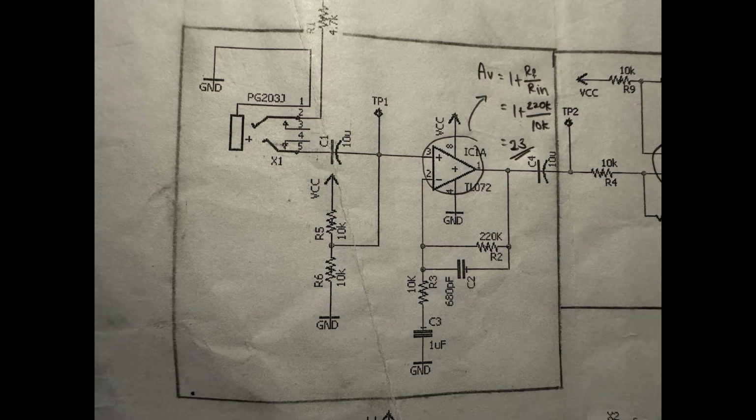The experiment was first carried out using a function generator set to 200 millivolts peak to peak at 1 kHz. Measurements were taken at different test points throughout the circuit using an oscilloscope to observe how the signal changes after each stage. After completing the first experiment, the same procedure was repeated using an input of 200 millivolts peak to peak at 200 Hz. The results from both experiments will then be compared to observe how the change in frequency affects the circuit.